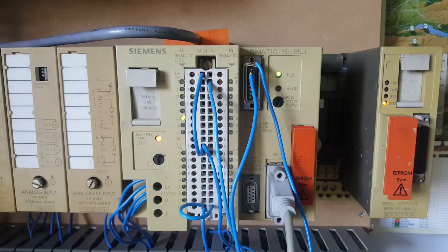So, to be able to measure these values in a PLC and display them as meaningful units, we need to scale the analog signal from the sensor. In order to do this, we need to know some information about the sensor, like is it voltage or current, the range which it can detect, the output characteristics like is it 0 to 10 volts, 1 to 5 volts, 4 to 20 milliamps, etc. Once we know this information, we can start programming.